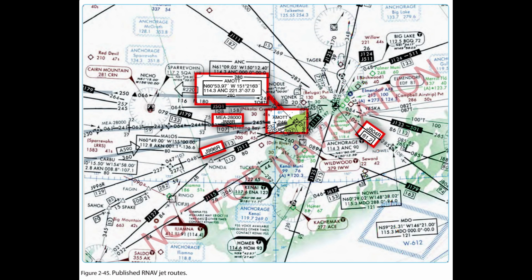Radar monitoring by ATC is required on all random RNAV routes. Random RNAV routes can only be approved in a radar environment. Factors that are considered by ATC when approving random RNAV routes include the capability to provide radar monitoring and compatibility with traffic volume and flow. ATC radar monitors each flight, however, navigation on the random RNAV route is the responsibility of the pilot.